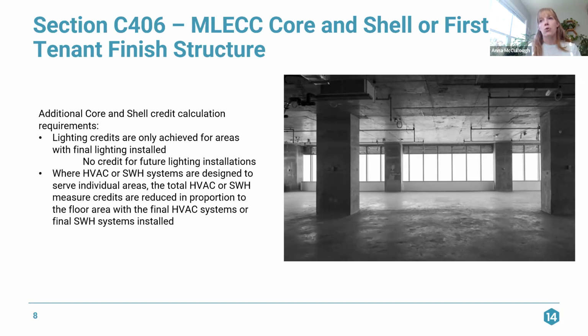Where HVAC or service water heating systems are designed to serve individual areas, so if you are putting in a rooftop unit that's going to be serving this northeast wing of your building because you know who's going to be in there and this is what you need to do for them, the total HVAC or service water heating measure credits are reduced in proportion to the floor area with those final systems installed.